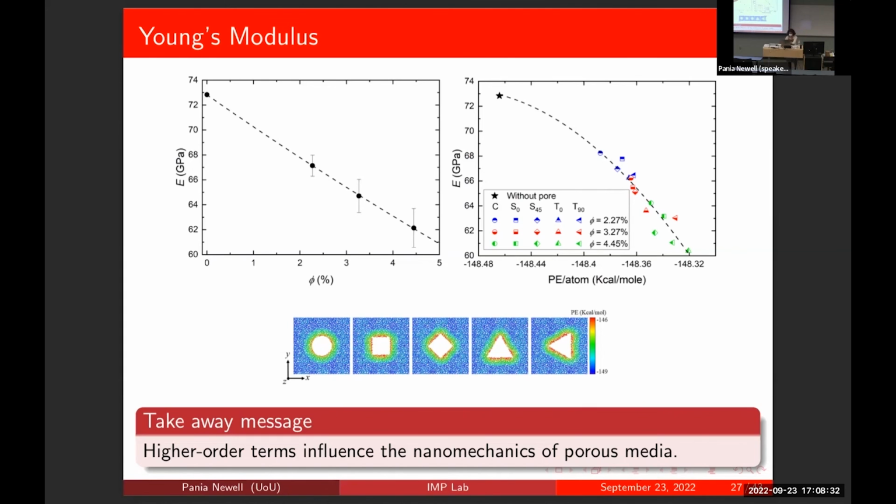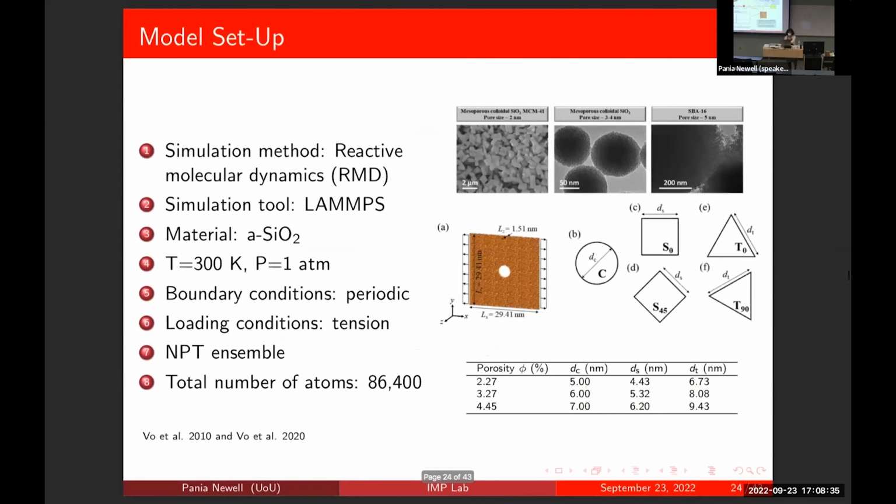We look at each of these unit cells that we are setting up here, and we extract the properties. So that means we assume that that is the distribution of pores, a periodic distribution of these. Yes, I put it here, the boundary condition: we assume periodic boundary conditions.